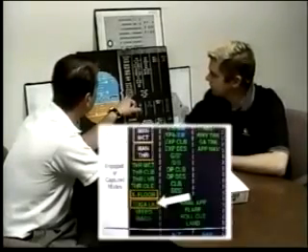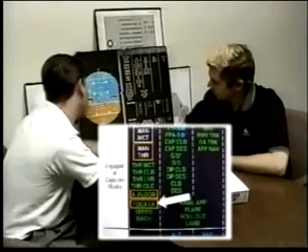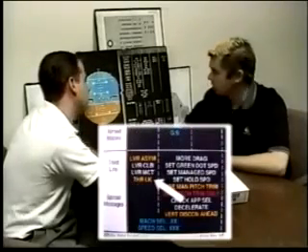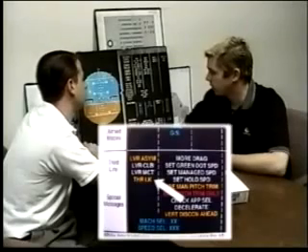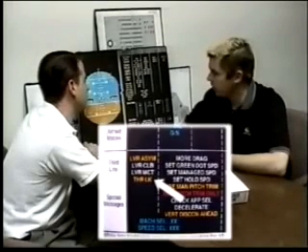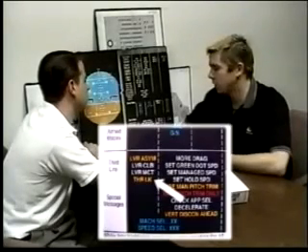How does TOGA lock differentiate from thrust lock? Well, TOGA lock is just as I described. It's an alpha floor function. Thrust lock, though, is when you've had the auto thrust engaged, and while it was engaged, the auto thrust function failed. It'll then leave the thrust at the last set EPR.